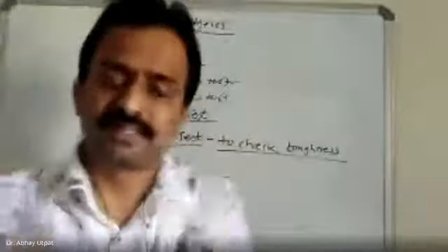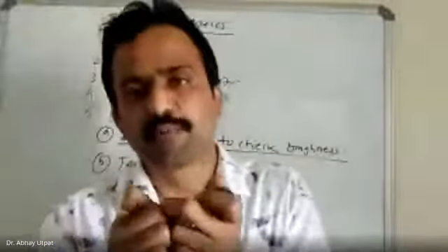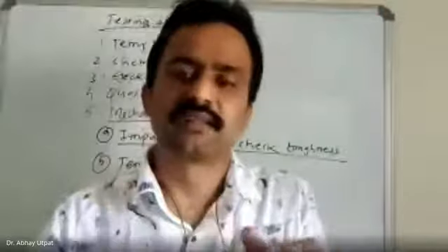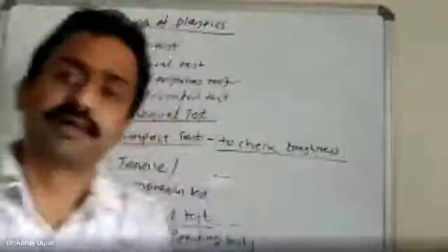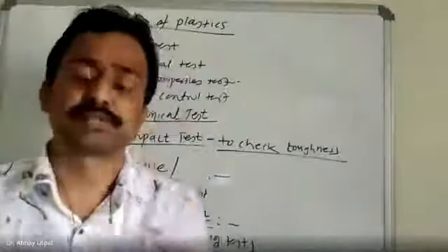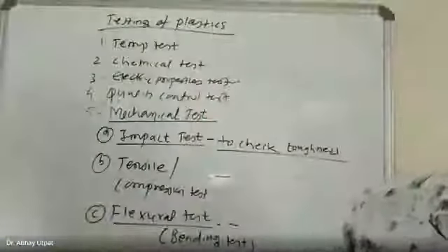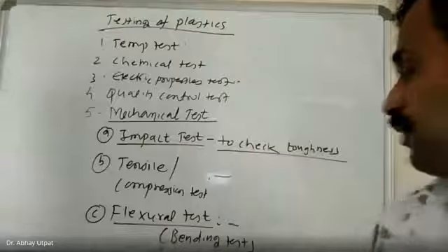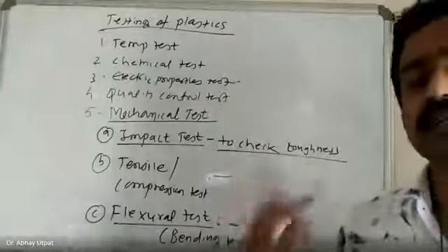If it regains its original position, we can say it is under elastic behavior, but it will not; it will form a crack. Up to the formation of that crack and the final deformation level, you have to apply the force. Flexural testing is one kind of bending test, and the strength of the plastic for bending is measured.